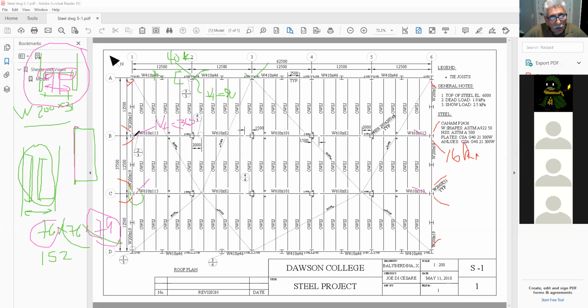The same thing here. Here, for example, this is the flange of the column. Now, if this flange happens to be 150 millimeters, I don't know what it is, I'd have to go look it up. I know what the column size is, so I have to look at the width of this flange. If I decide to use 76 by 76 steel angles, well, 76 is going to be out here and 76 is going to be out there.